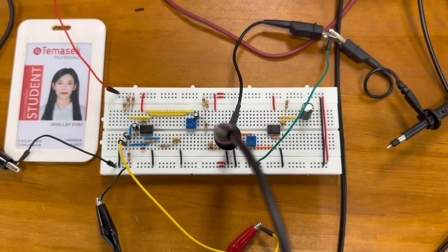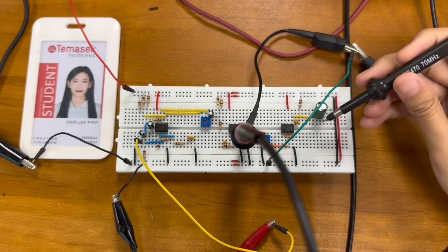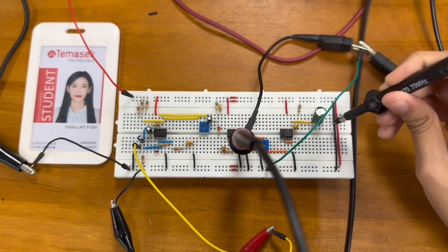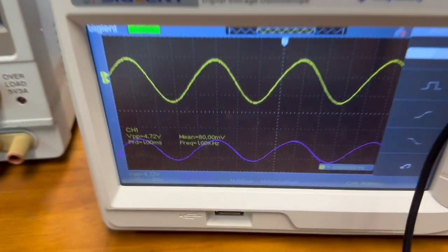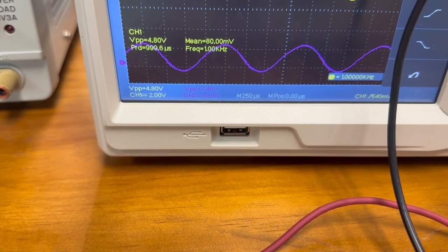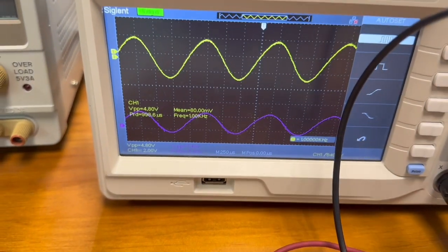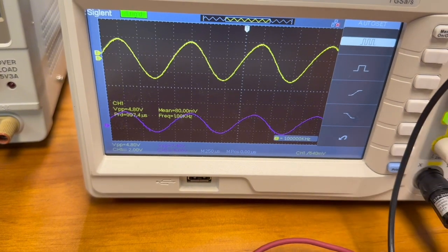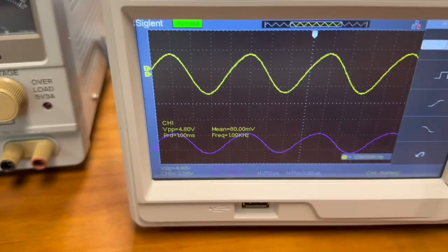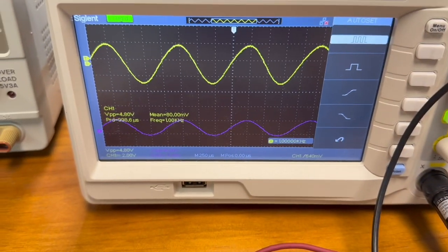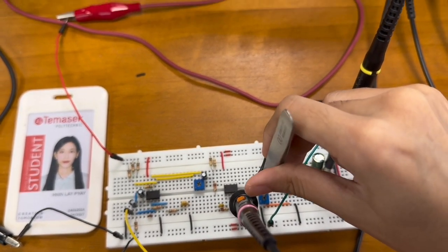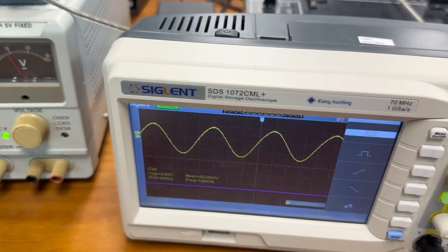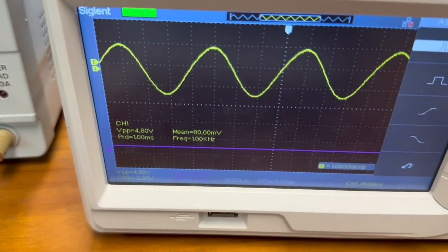To set up stage 4, we will do the same as earlier by keeping TP4 at channel 1 and all patches untouched. We will then place the channel 2 probe of the oscilloscope to TP5, then we get an output voltage of around 7 volt. By adjusting trimmer P2, we can control the output at TP5. Final output is maximum as a sine wave attained without being saturated.